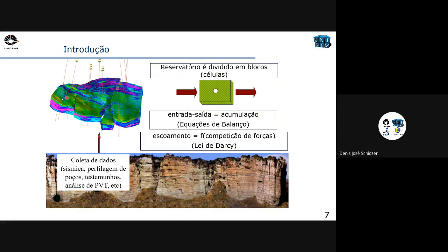Once I have the boundary conditions, which sometimes are for the reservoir, such as no-flow boundary conditions or a fracture, or even a well that's taking fluid out of the block or putting fluid in the block, we're going to learn how to use these mathematical equations to write how much flux is coming in, going out, and accumulating in the blocks, which is governed by Darcy's law, which you have seen in Reservoir 1 or even in other courses in our classes.